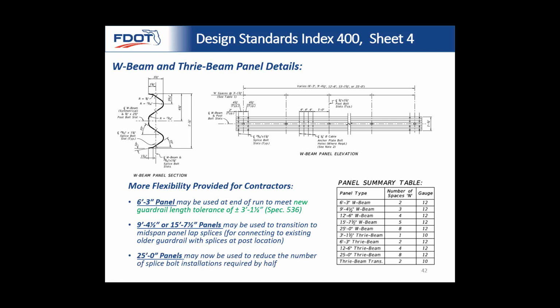Now 25-foot panels are now available. Previously, maintenance crews, I think, thought that you always have to replace the exact panel in kind. That's not necessarily true. So they can replace a 25-foot panel with 2 12-foot 6-inch panels, and the 12-foot 6-inch panels fit on their trucks.